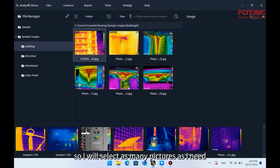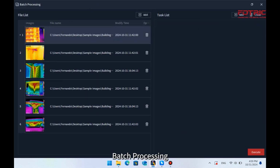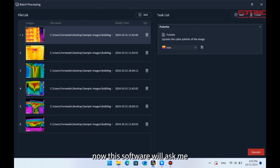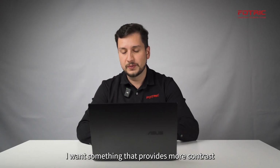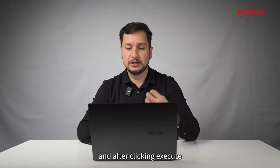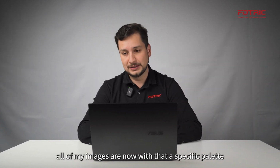So I will select as many pictures as I need. Click on Tools, Batch Processing, and the task that I will apply on this instance is Change Palettes. By clicking here, now the software will ask me what palette I want to use. So I don't want iron, I want something that provides more contrast, probably a rainbow. And after clicking Execute, all of my images are now with that specific palette.